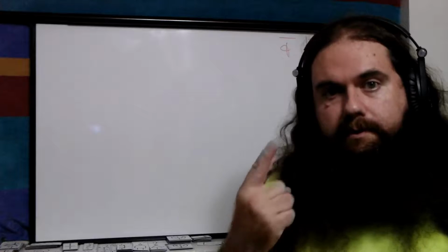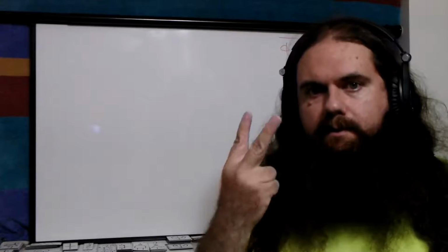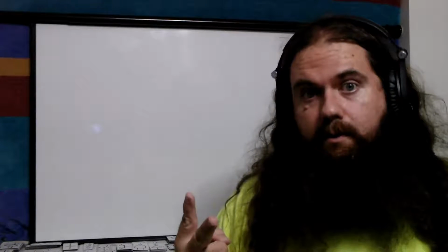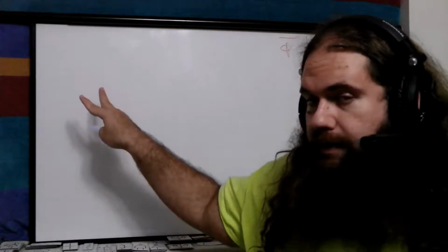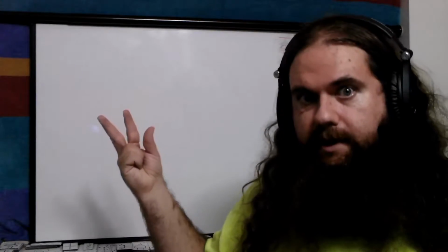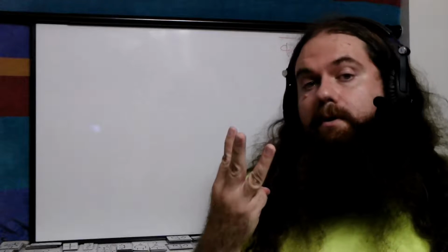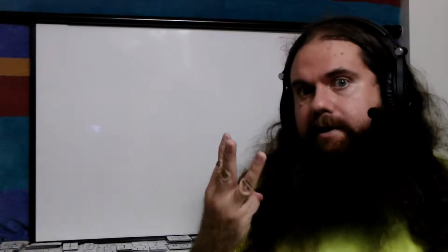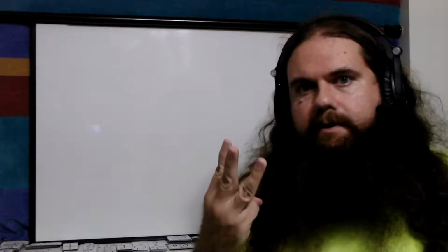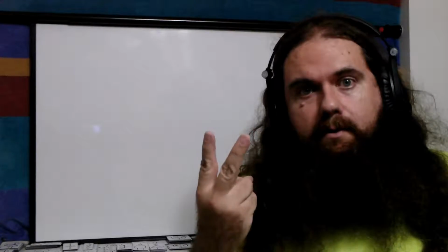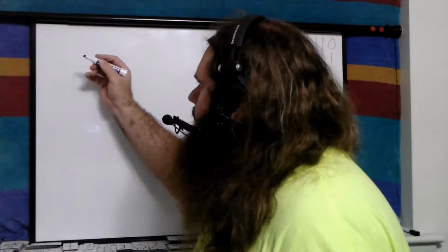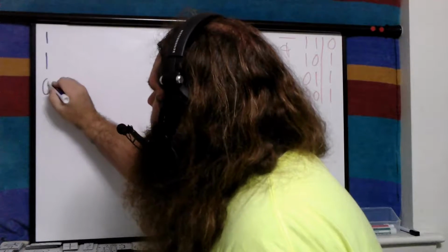There you go. So we'll do AND. NAND we already have. We'll do OR. But NOR, not OR, is just OR with an inverter. So whatever we do for OR, add an inverter, which can be a NAND gate, and you're done. XOR. Well, XNOR is just not XOR. So that with an inverter. So we only need to do 3. AND, OR, XOR. The truth table for AND is 1, 1, 0, 0.